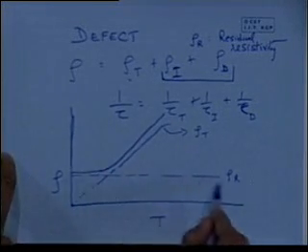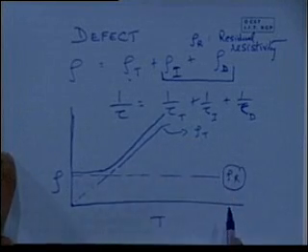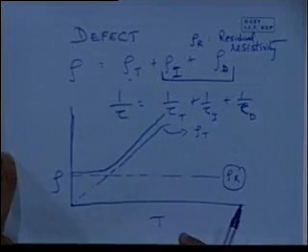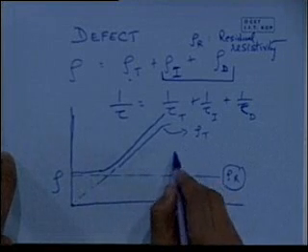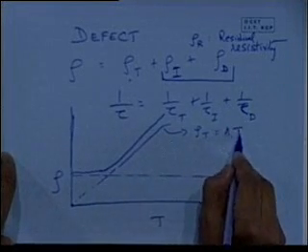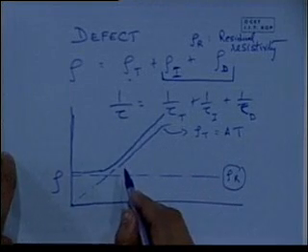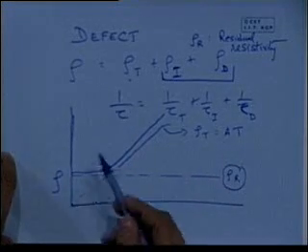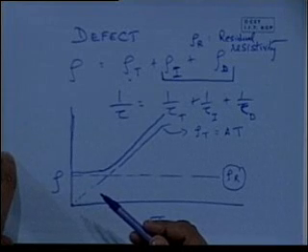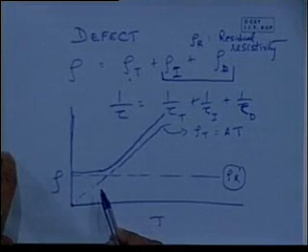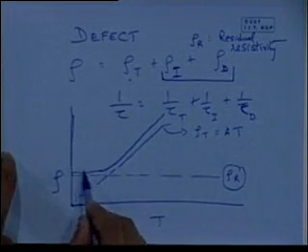So I have two mechanisms, a residual resistivity term that is temperature independent, and I have a term, rho t is equal to A times temperature. So the overall resistivity in this case is the sum of these two terms. So it should be a straight line. What about here? Yeah, if you are adding both lines, meaning rho r and rho t. Yeah, I'm saying there is actually another.